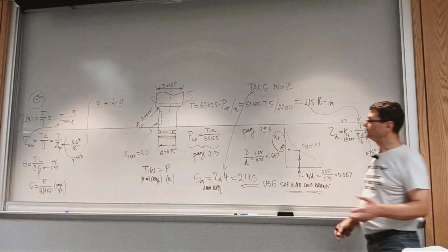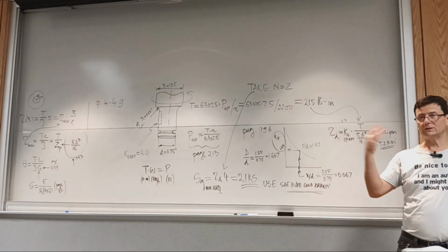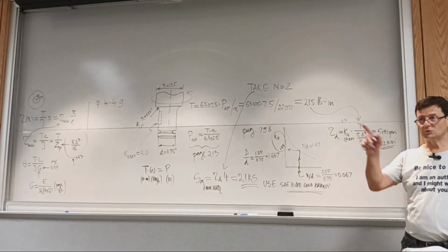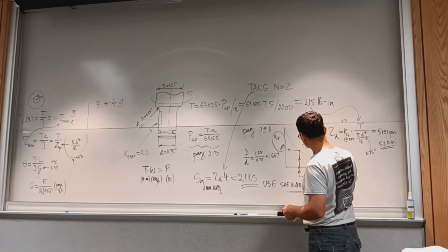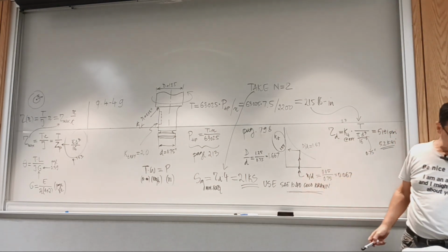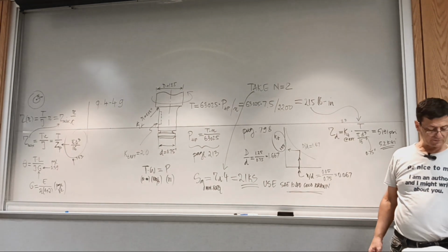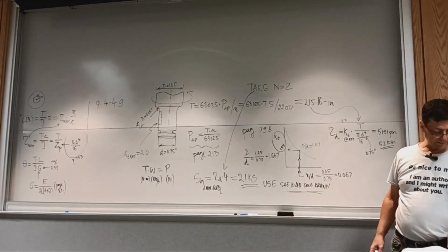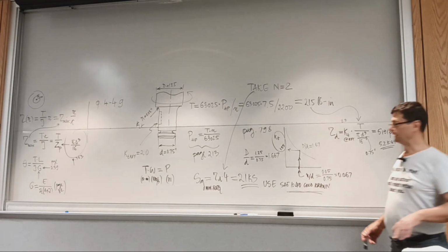Okay, so because you need to work with the chart, there's a bit of trial and error. Actually, no, you solve for the required Kt at the hole. And you read the chart in reverse now. So you go with the required Kt, and you go in reverse, and you can calculate the diameter of the hole. I'm pointing to the wrong graph, but do you understand? This is for problem 50. The problem is designed to ask what would be the maximum diameter of the hole, noted a now, that limits the torque due to the stress riser of the hole, same as for the step of the shaft. And there you go in reverse.